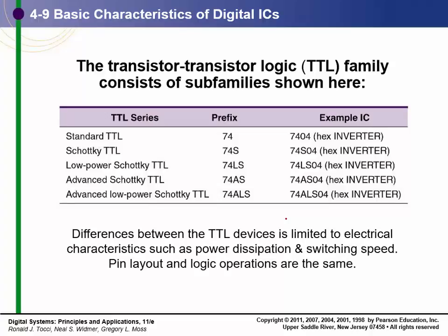It all depends on how close to the specifications the designer did that, how wide of a glitch he allowed to be in the final circuit. If there were no glitches and the circuit was well designed, you could pop in the fastest chip in the world. Theoretically, you should always be able to go from a 74 to a 74ALS and not have problems. But some circuits, you will have problems.